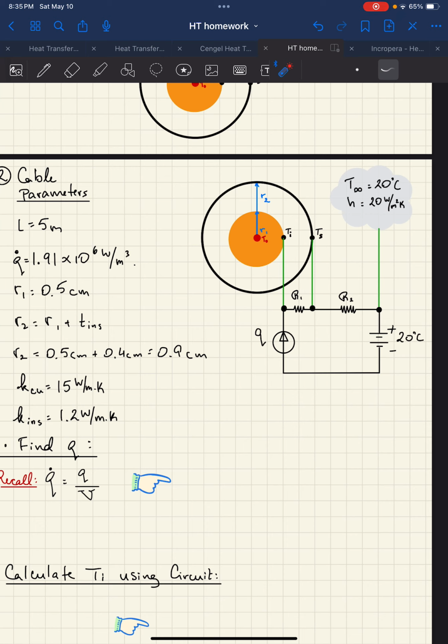It's providing energy, it's providing heat. Okay. In this portion here of the insulation, you can use the thermal resistance due to conduction, and on the outside with the air, thermal resistance due to convection. Now here, this thermal resistance combines the effects of convection and radiation, so you don't have to add a radiation thermal resistance in parallel. I made it so that it's all in one.